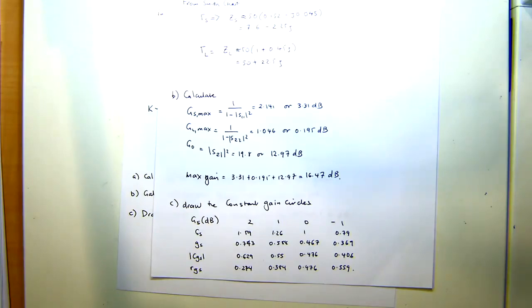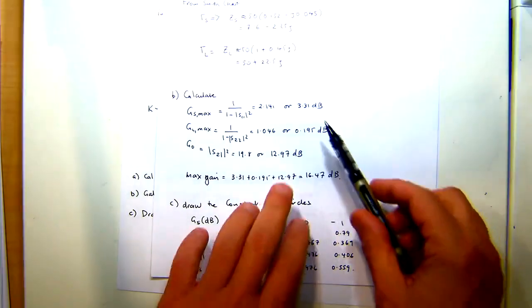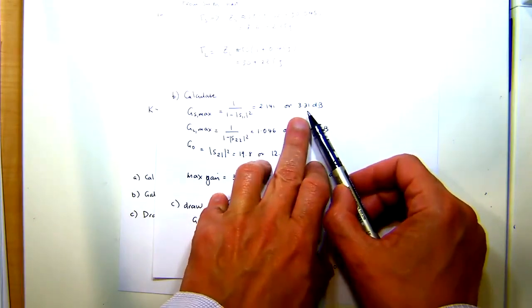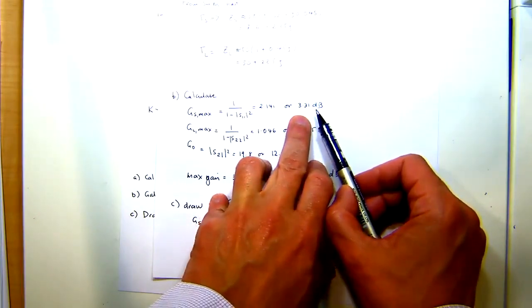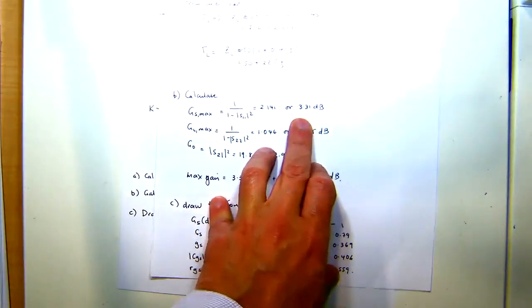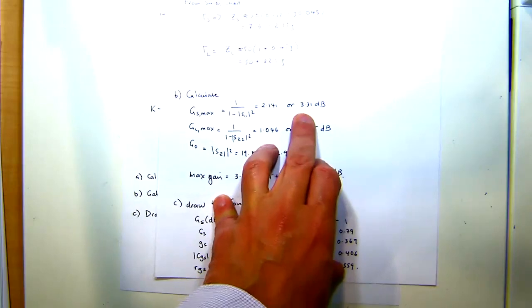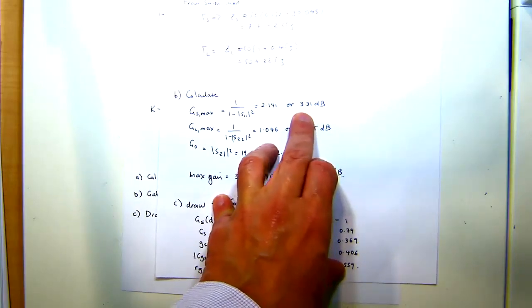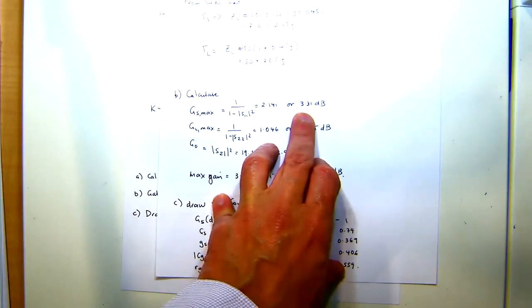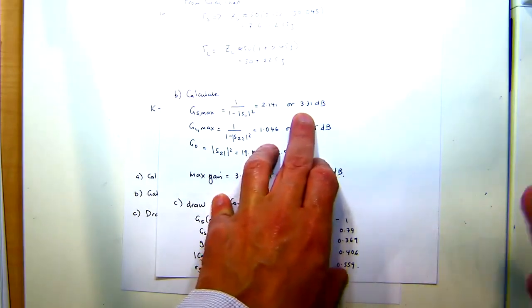I chose them. I randomly chose them, right? Why did I randomly choose them? Well, my optimal gain for GS is 3 dB, right? Let's now choose values which are less, which show me which regions and what impedance options I have available in order to achieve those levels of gain, right? That's all I'm doing, right?